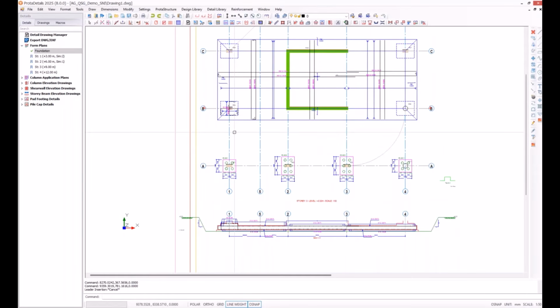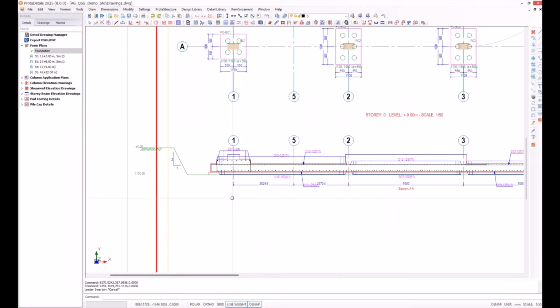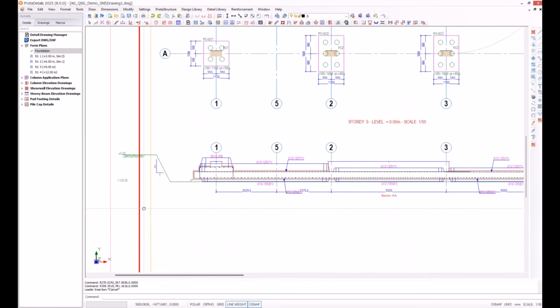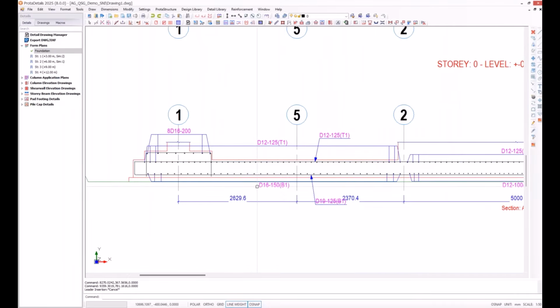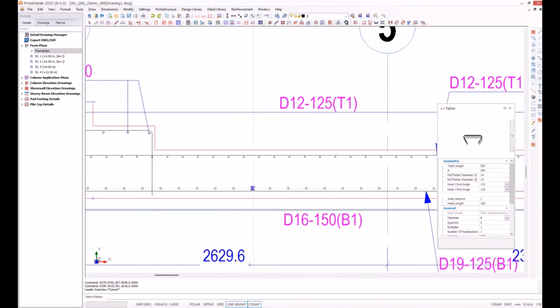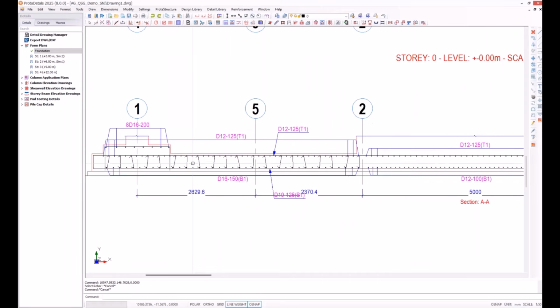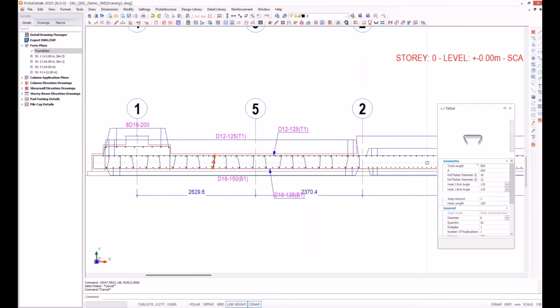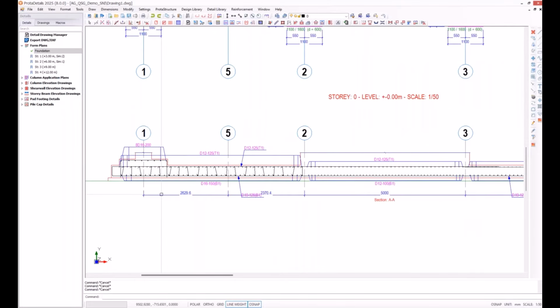And of course, before coming to the best part, let's finish this sheet. Maybe for some specific reason, I would like to add tie bars on this area only. Okay, just select them, and tie bars are produced. And we have a lot of different features and options like this, and these are all intelligent rebars, as I said. I will show you what it means by intelligent rebar.